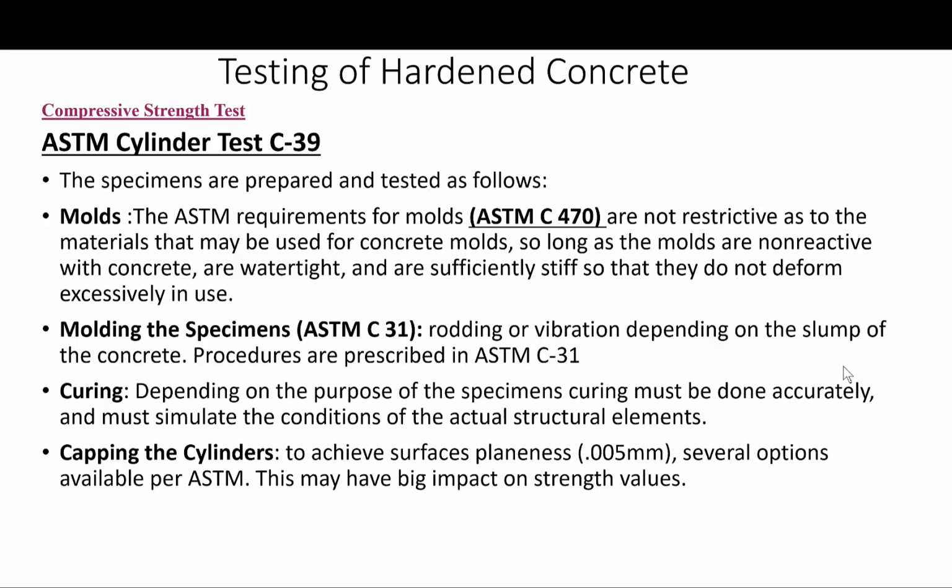And again, in certain cases, especially when we use the cylinders to determine when the concrete members can be stressed, I would advise these cylinders to be placed, stored, and cured in the exact same manner as the concrete member in question. Okay, that will help eliminate any other variables that could happen and really compromise or impact the test results.